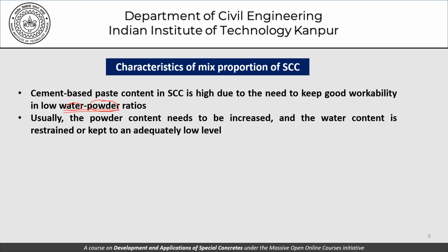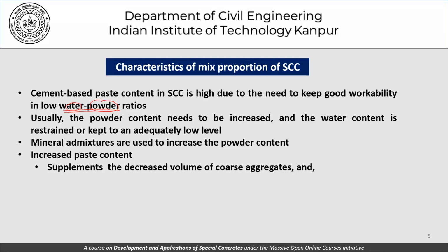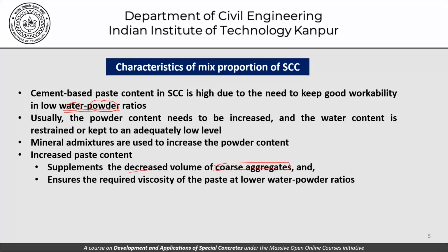Moving forward, the powder content needs to be increased and the water content is restrained or should be kept at an adequately low level. Mineral admixtures are used to increase the powder content, which increases the paste content. This leads to a decreased volume of coarse aggregates and ensures the required viscosity of the paste at the low water to powder ratios.